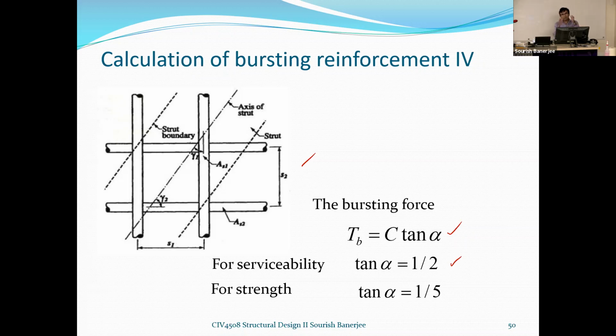For example, think of a divergent stress field: it will increase if there is no crack. Once cracks start appearing, that divergent stress field will be more like a prismatic one. And as a result, when it comes to strength, we get less effect of the bursting force.